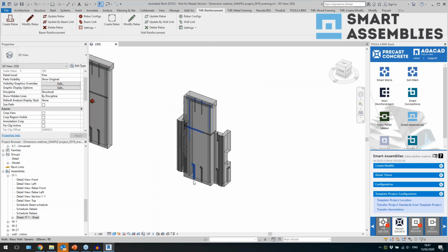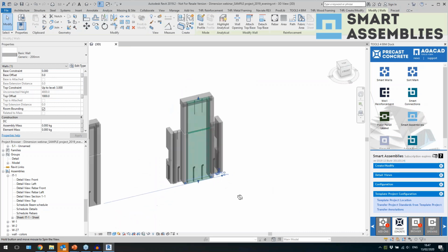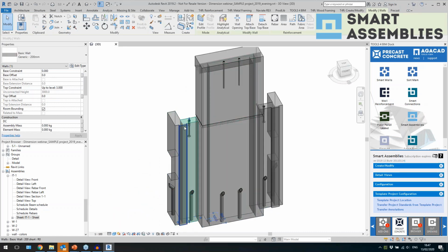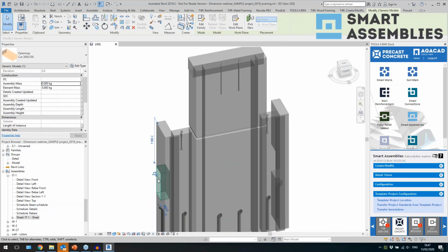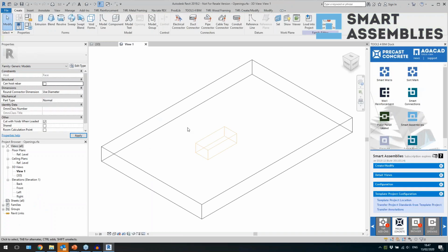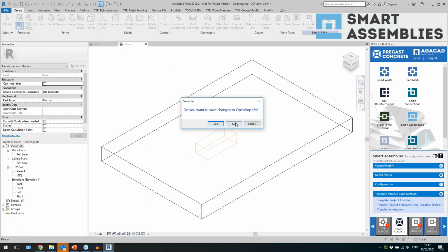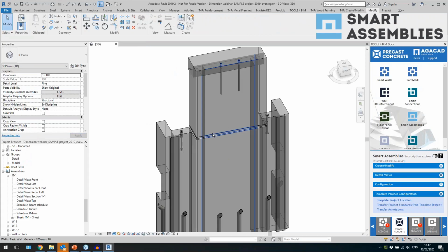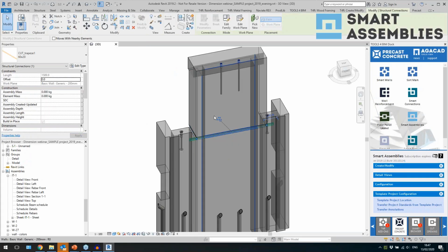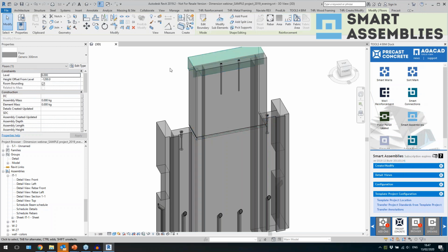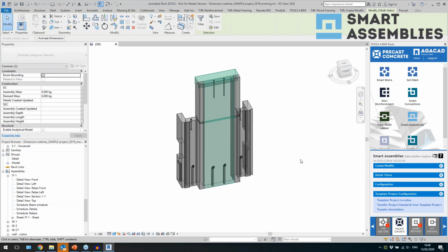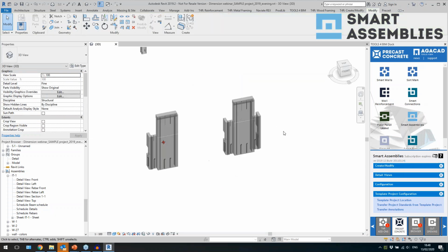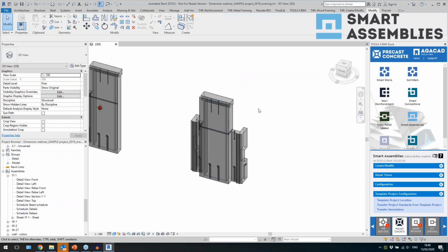And another thing that I would like to show you is, what if I have one wall, another wall, another wall, another wall, detail, detail. So I call them detail, but basically this is a face-based family, right? Most of them I use line-based or point-based families. Over here are some kind of cuts. This is a floor actually. So what would happen if I would select these and create an assembly? It would create two assemblies for me. So that's not okay because this is produced as one piece, for example.